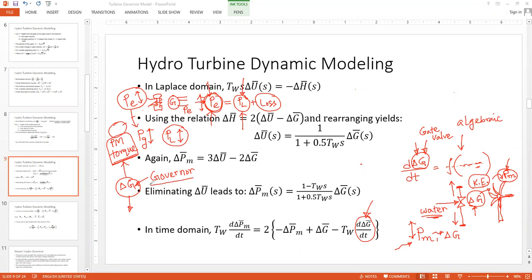Now, when will the governor start to act? This is the next question. When or how will it sense that it has to change this gate valve positioning? So the job of the governor will be to sense. Where is the change actually happening? At the starting point, where is the change? The change is occurring at the load end, right? And to cater for that change, you have to change the PE. And that will be done by PM and through the governor gate valve positioning.